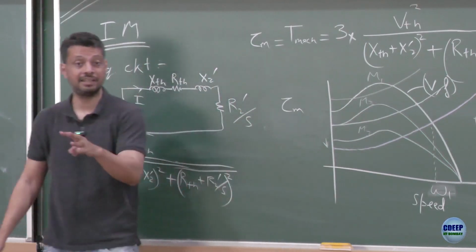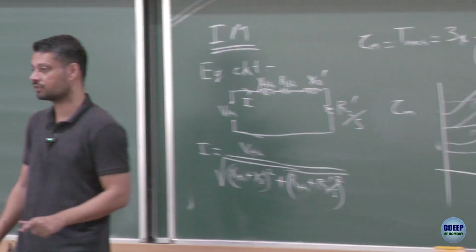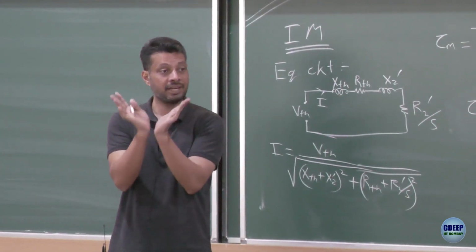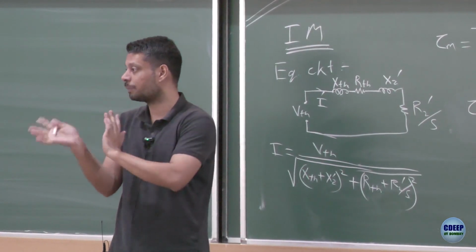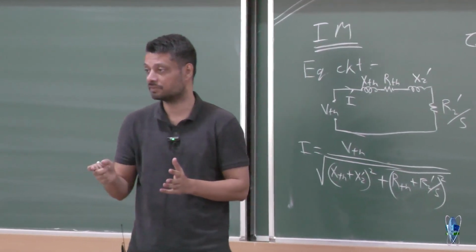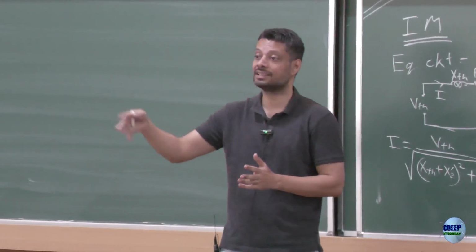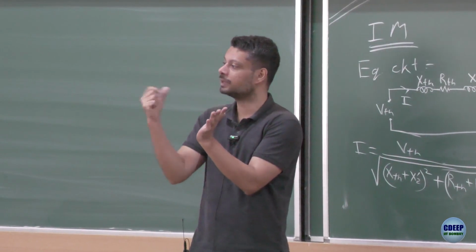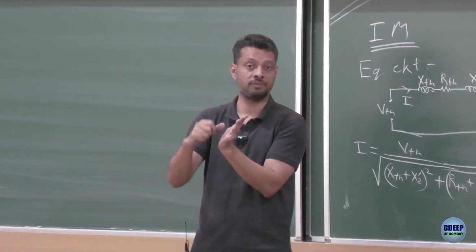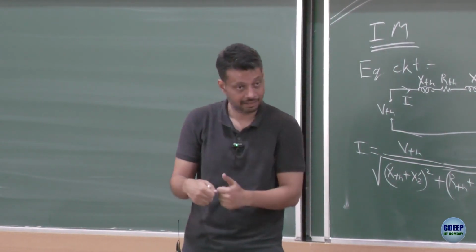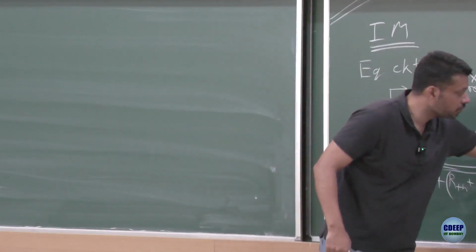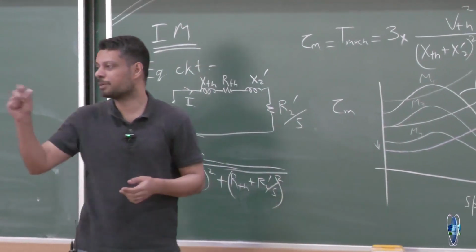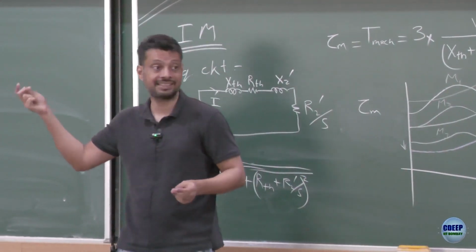Because this is not a 3-phase induction motor, this is a single phase induction motor. So the orthogonal component of the current is produced because of the capacitor, because the capacitor provides a 90-degree phase shift, and that is used to run the other winding, and therefore you get the torque. Over a period of time the capacitor becomes weaker, the orthogonal component becomes weaker, the starting torque becomes even lesser, right? And this guy would actually move down below the starting point of the fan itself, and therefore you will not be able to start at 1 or 2, it just starts at 3 or 4.